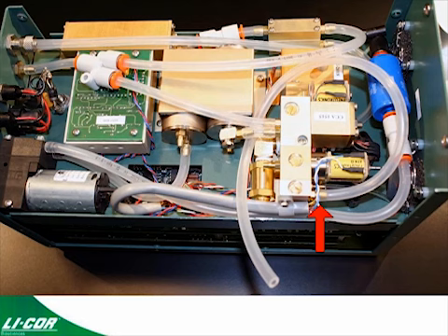Connect the new tube number 3 to the inlet side of the CO2 mixer and feed the tube underneath the tubes coming out of the second buffer volume. This location will protect this tube from damage when you reinstall the shell on the carriage.